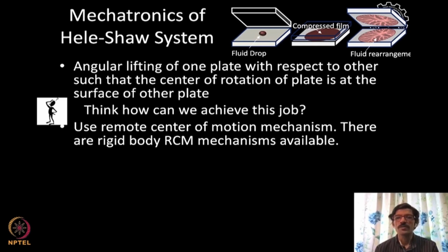So now how do we overcome this problem? Like we have seen, if you want very accurate motions without friction, you need to think about these motions without rigid mechanical joints. Without joints, the option, as you remember from the class, is compliant mechanisms. So flexure mechanisms are what you will think of using. Then you need to check whether there are any compliant mechanisms available in the literature which can do this job. Then you may find some things, you may plan and use that.